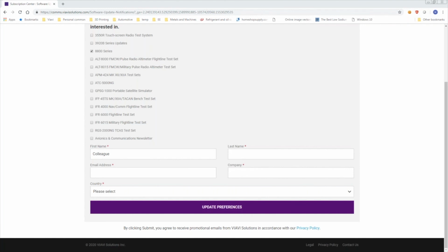Mike, on your auto test, your APX 4500, there have been some changes to auto test for the APX radios, and I think the PA bias alignment was one of those things we had to make some changes on. If you don't have the current software, what's currently on the website on your test set already, I would recommend going ahead and starting there.